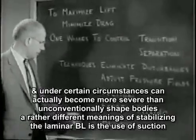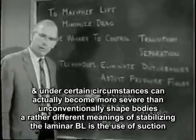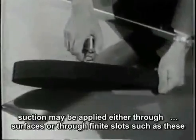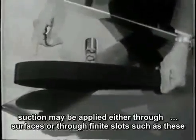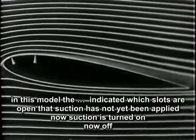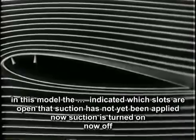A rather different means of stabilizing the laminar boundary layer is the use of suction. Suction may be applied either through porous surfaces or through finite slots, such as these. In this model, the arrows indicate which slots are open, but suction has not yet been applied.